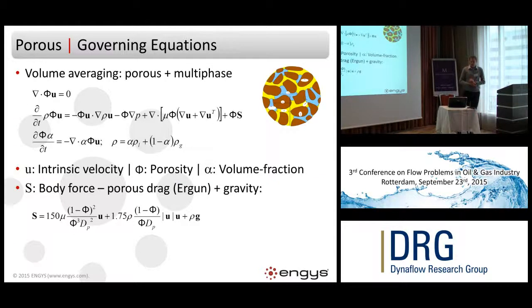Then in the isothermal solver, we have support for arbitrary heterogeneous porosity fields. The idea is that you can specify any varying porosity field, whether it includes sharp discontinuities in porosity or not, and the solver should be able to handle it. At this stage, it doesn't take account of capillary effects, so it can't really be used for gas sparging underground, those sort of applications. Something that can be added.